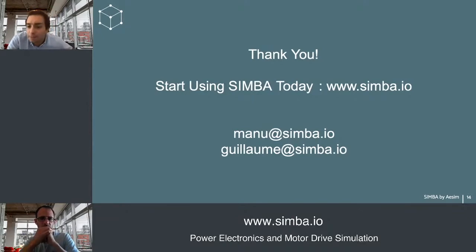Anyway, another question: can SIMBA import any SPICE model or XML from power devices? So SPICE model, we don't support that for now. And I don't think we will, to be honest. But it might change. However, because we don't want to have a SPICE solver, because SPICE solvers are very good and widely used, but they are very slow.